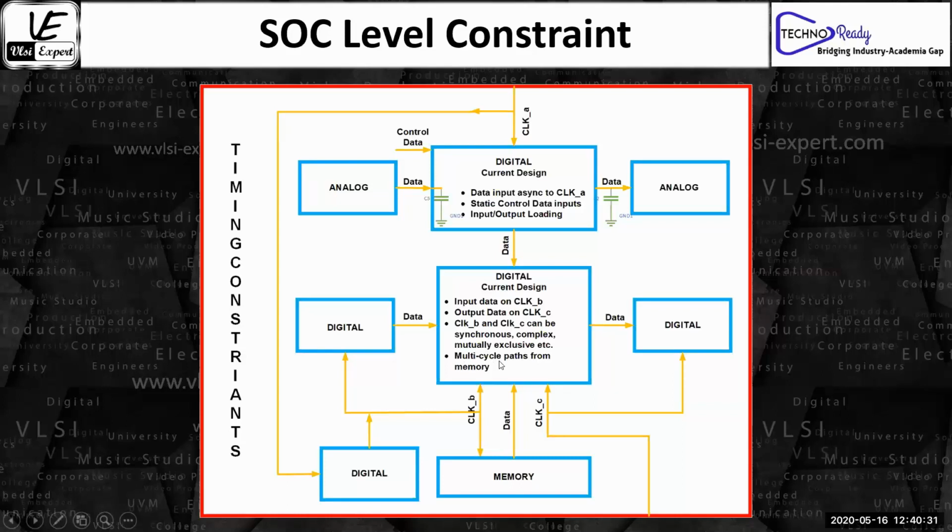For constraints, we are only considering timing constraints, not area and power constraints. Area, that's a very good question. Usually the area constraint is also there, and we will try to specify it. It depends. The prime focus will be on timing constraints. Area constraints are usually out of hand to begin with.